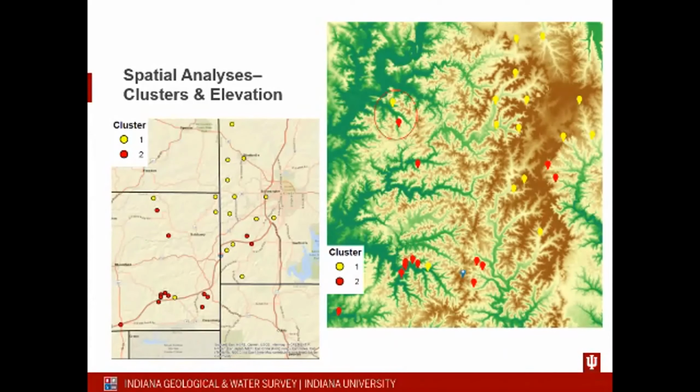And so we think that this could potentially be due to difference in the bedrock aquifer, which we talked a little bit about on the previous slide, or it could be residence time in the aquifer, which can be a function of either a larger aquifer feeding the higher conductivity spring, or possibly tighter permeability or smaller fractures causing that higher conductivity spring to have stayed in the aquifer longer, which allows for more of the water-rock interaction and mineral dissolution. Or it could be none or a combination of all of these. So hopefully with, like I said, more spring sites, we'll be able to tease out some more of these factors.